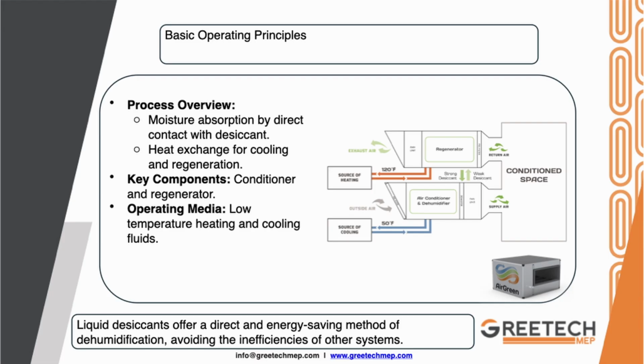However, for more commercial applications, the system is connected to a simultaneous cooling and heating system, or what is known as 4-pipe chillers that provide hot and cold water simultaneously. This is not possible when using the desiccant wheel, because the system in this case requires temperatures of more than 170 degrees Fahrenheit, so in these cases a boiler is required.